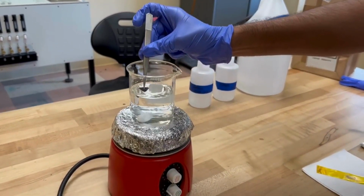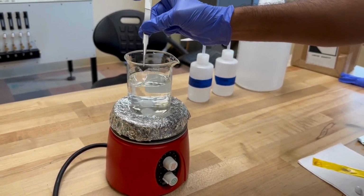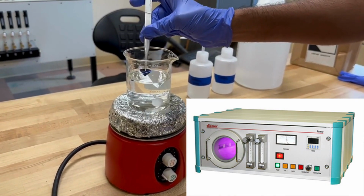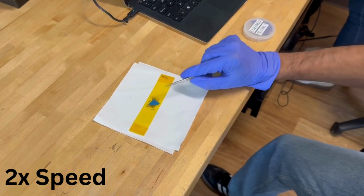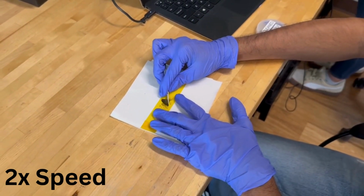Next, an oxidized silicon substrate is cleaned either by baths of acetone, IPA, and deionized water, or by oxygen plasma treatment. The substrate is then placed onto the tape, oxidized side down, and gently pressed together with tweezers.